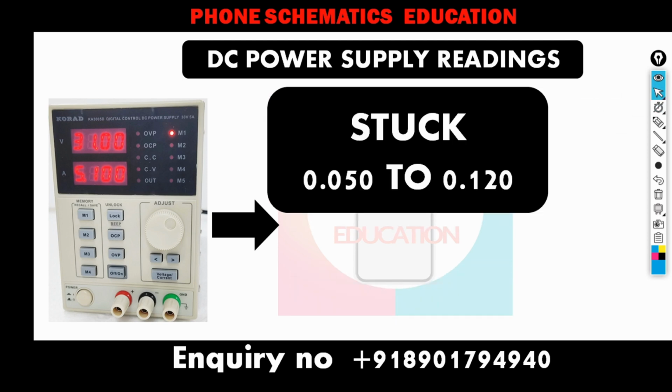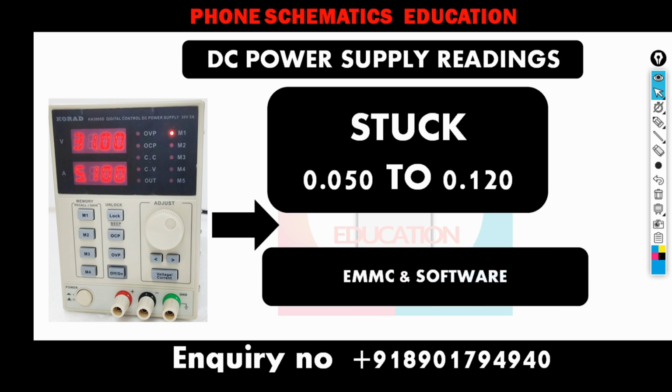Now, stuck. When you connect the DC power supply, no consumption. When you try to press the button or on off button, it takes 50 to 120. Let's suppose in some phone the reading is stuck at 70, or stuck at 80, or stuck at 85. These types of issues you all must have noticed, right? Then the problem comes from the storage IC called EMMC or UFS, right?